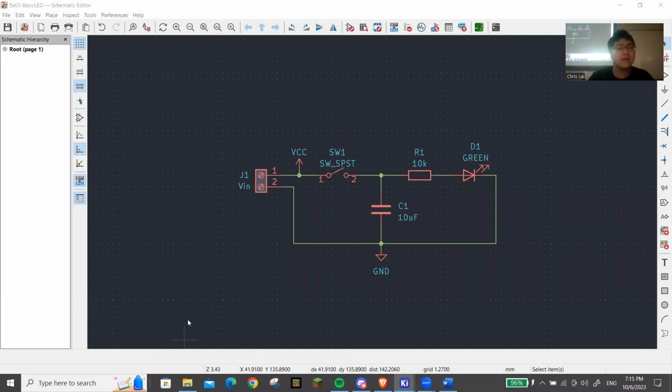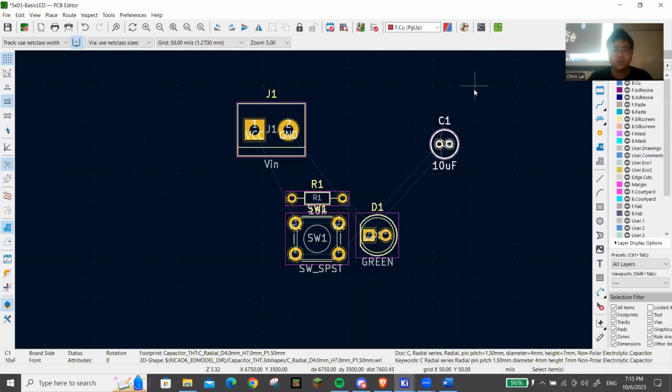How can you use mils versus inches? To convert units, you will go into PCB view. On the left sidebar, you will see a bunch of conversion units on the top. You can see inches, mils, and millimeters, and you can just swap between the units. So if you're in inches like this, you can just click on mil and you can go into mils measurements.